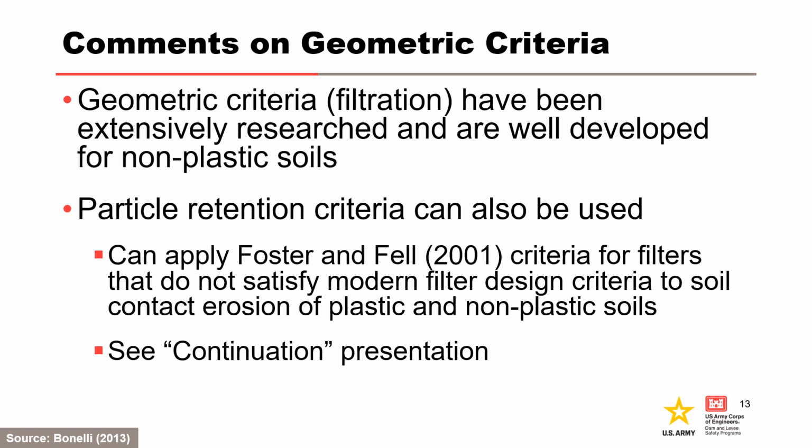The geometric criteria for filtration have been extensively researched and are well developed for non-plastic soils. Particle retention criteria can also be used. The no erosion condition and the application of Foster and Fell 2001 for filters that do not satisfy modern filter design criteria to evaluate soil contact erosion of plastic and non-plastic soils are discussed in the continuation presentation.